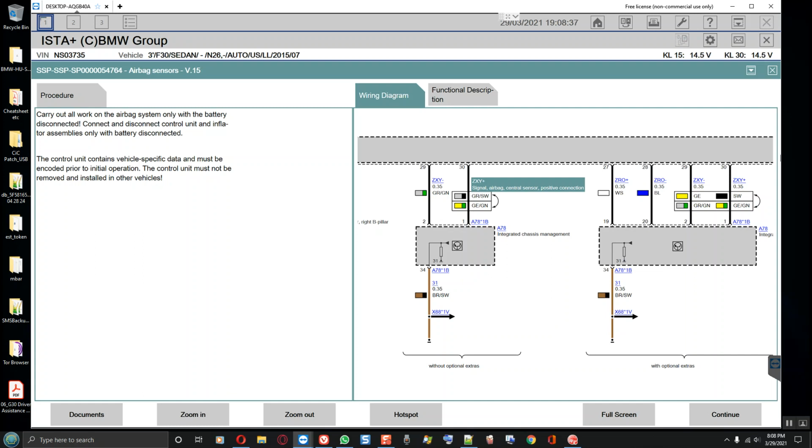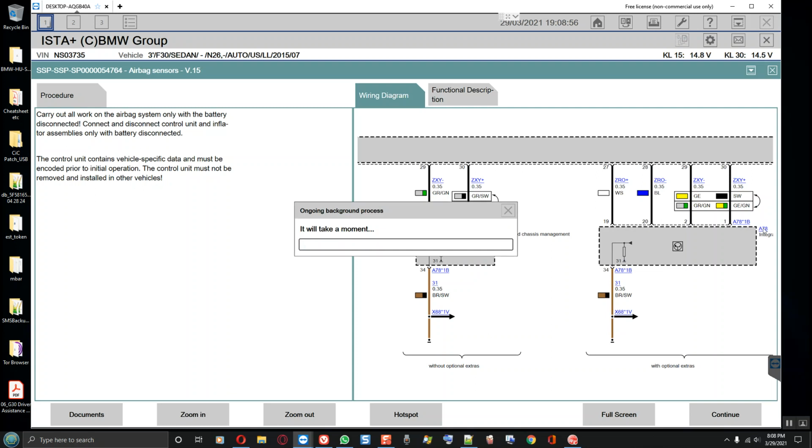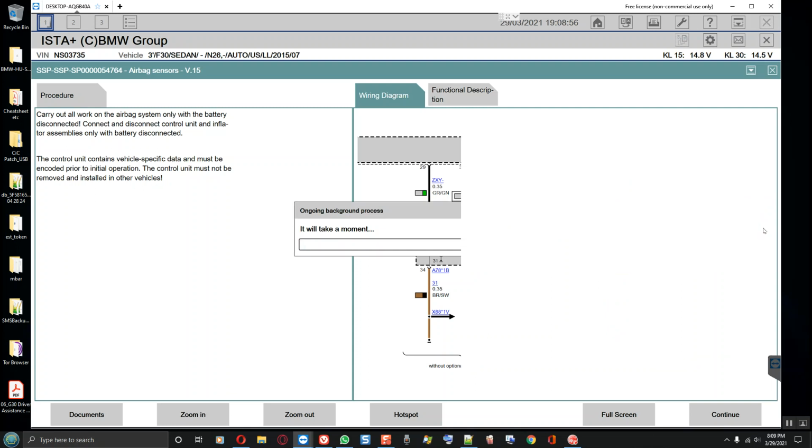Yeah, the ICM is the same ICM that's been in the car from factory. Let me look at the pins real quick and see if 19 and 20 are used or not, and I can tell you which one it is. Give me 1 second. In the meantime, I'm gonna turn the car off for a second and disconnect the battery so I can unplug the ICM and look at the pins real quick.